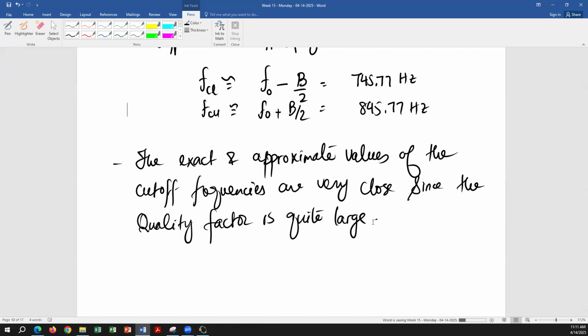The plot is coming from your transfer function. When you're plotting from the transfer function, based upon how many points you're plotting, if you are trying to figure out your cutoff frequency from the curve, that depends on whether your step size is 100 hertz or 10 hertz.